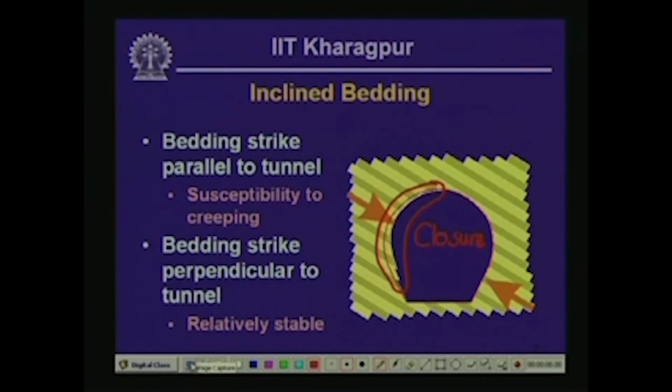Here the rock that was transected by the tunnel was basically phyllite, which is a ductile type of rock, and the tunnel was affected by closure as well as another type of problem which we are going to see a little bit later on.